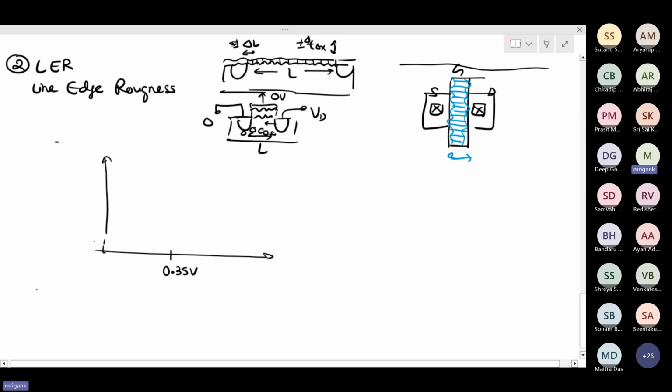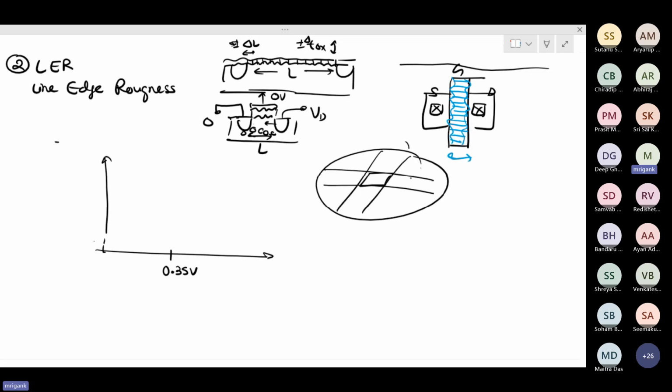But now, because of the random variation, on that particular chip that you took out from that big wafer, right? You cut this wafer into small chips. When you are on this chip, there are suppose 100 MOSFETs, maybe hundreds and thousands and maybe millions of MOSFETs, but assume that right now 100 MOSFETs. You measure the VT of each of these MOSFETs. Suppose you have some circuit through which you can measure the VT of each of these MOSFETs and plot the histogram over here. That means the number of MOSFETs having VT exactly equal to 0.35 volt.